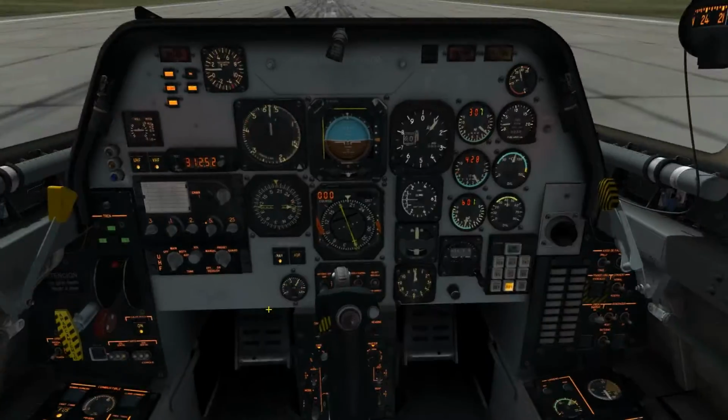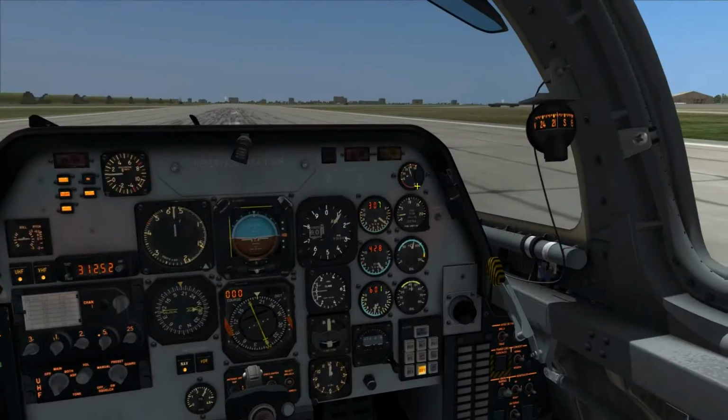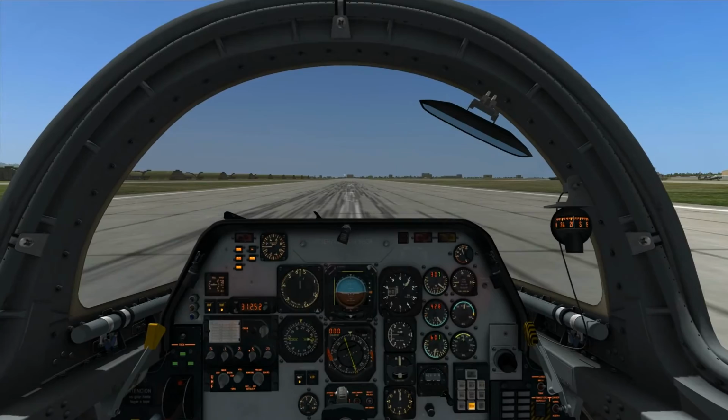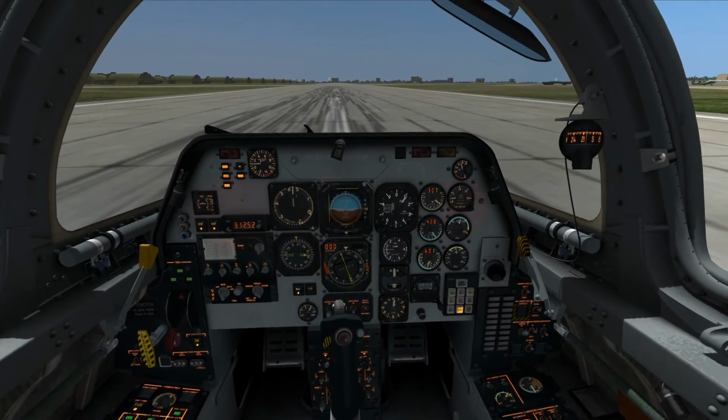Engine instruments check. Again, one more time. Green, and green. Voltage check. Minimum 28 volts. Checked. C-101 cleared for takeoff. Runway with no number. Wind calm. And now we must respond. Fine. We just finished the before takeoff checklist.